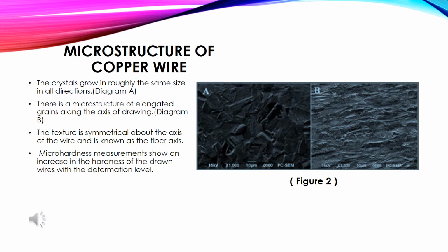A lower melting point mixture of pure copper and cuprous oxide, called a eutectic, forms in the open spaces between the dendrites. The eutectic particles are usually dark globular bodies dispersed in a copper background. The cuprous oxide particles form a network outlining the dendritic cells. Pores, seen as dark spots in the microstructure, are also present in the as-cast material.